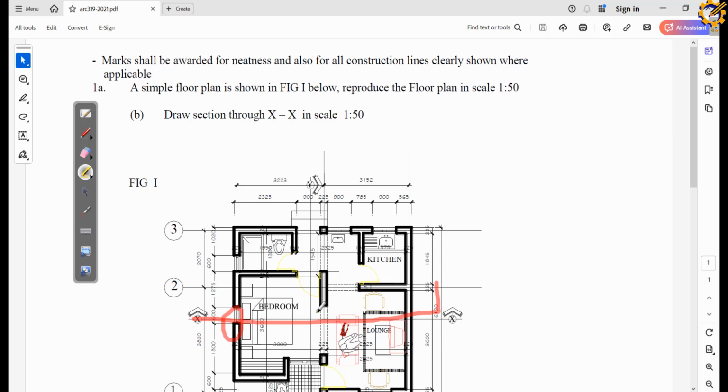It cuts across this area, which is our beam, and under a beam there is a foundation wall. So then it cuts across this wall also, the third wall. Do you see that? That is the reason why we'll be having 3 foundations shown in this particular sectional view, because it cuts across this, and this.